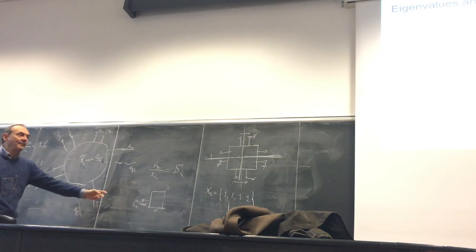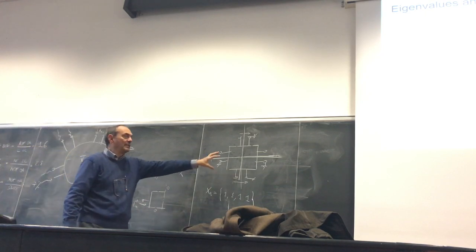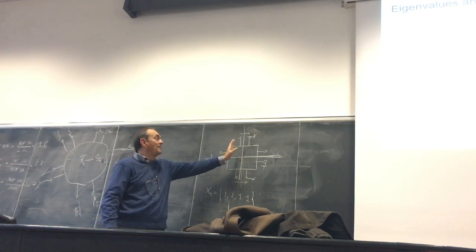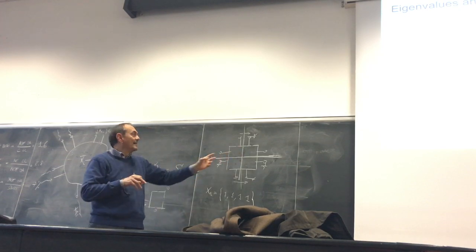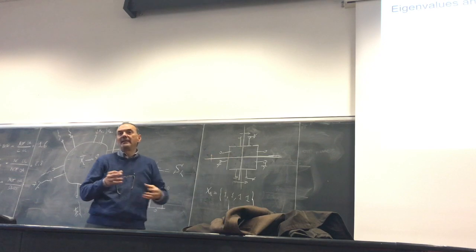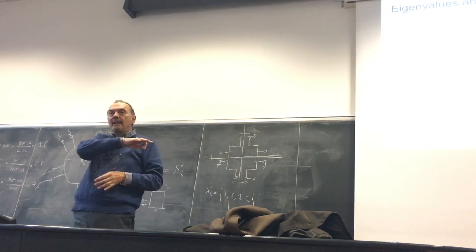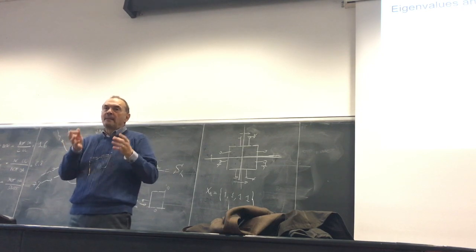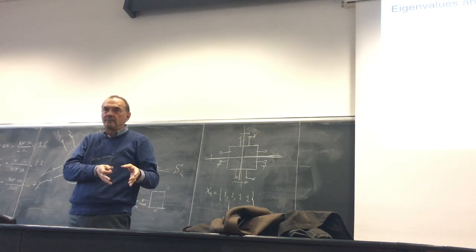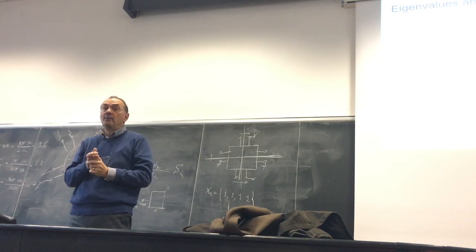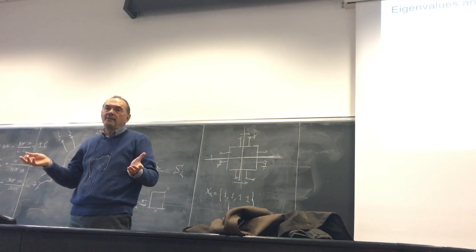So I can obtain the eigenvalue corresponding to the eigenvector I have used for exciting my network by extracting the part of the network which remains once I have inserted electric or magnetic planes associated to the eigenvector, and then observing inside this network the value of the reflection coefficient, I have the eigenvalue.